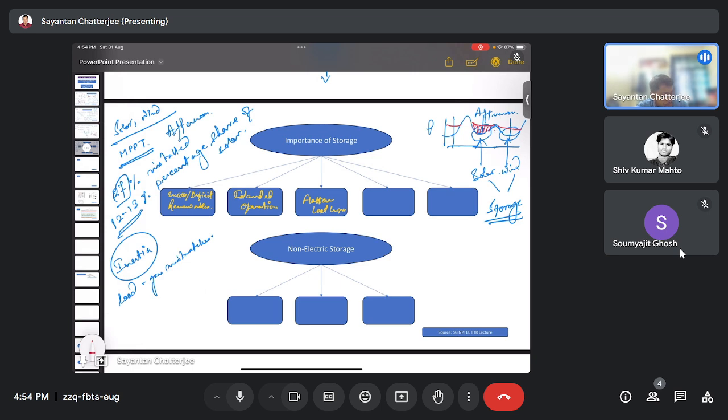Again, during this period the batteries can deliver power, and ultimately this amount of power that was previously required to be delivered by the synchronous machines can be supplied by the batteries, so we can reduce the generation of the synchronous machines during these periods once these things become a global strategy. At least in the Indian context, if these strategies are entirely taken up, then we can curtail the peak by delivering that excess peak from the batteries or storages, not only batteries.